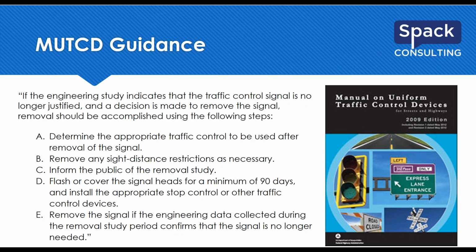Yeah, as Brian just mentioned, there are no real guidelines from a federal level that tell you exactly when to take it out. Different states have different recommendations or guidelines. For example, in Minnesota, the Minnesota DOT says that if you are getting less than 60% of the volumes for a warrant, then it's probably a good idea to take it out. That's for the warrant thresholds, the volume warrants. Yep. If you're at 60 to 80% of those volume thresholds, then it's kind of in a gray area. It depends on your judgment, maybe doing a study about it. And if you're meeting 80%, it's probably a good idea just to leave it in.